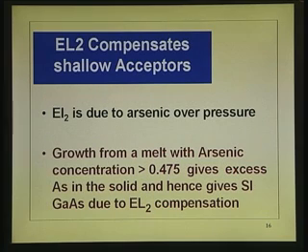EL2 is due to arsenic overpressure. Growth from the melt with arsenic concentration greater than 0.475 gives excess arsenic in the solid. I just put that diagram here.